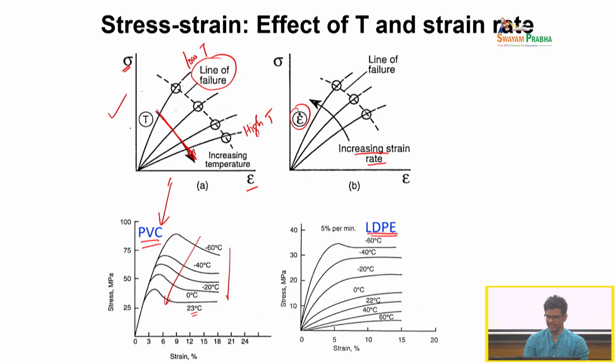So I think the temperature dependence is also shown for low density polyethylene. So temperature is increased from here to here. The material remains stronger, more stiff at low temperature. When you go to higher and higher temperature, the material becomes softer, and then the stress strain behavior can become very, very dependent on temperature. So it is very important to know the operating temperature of the polymer, because it will dictate its mechanical behavior. These two are not decoupled, these are not different things.